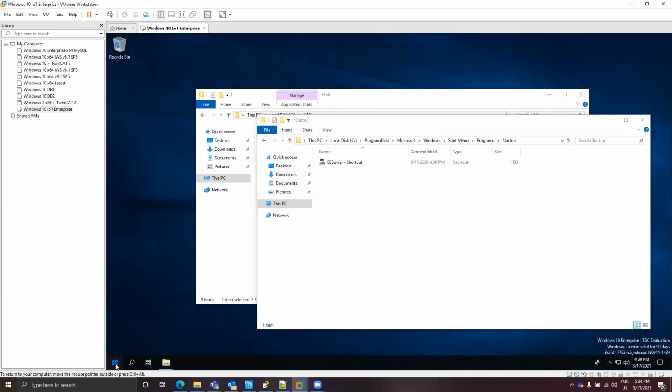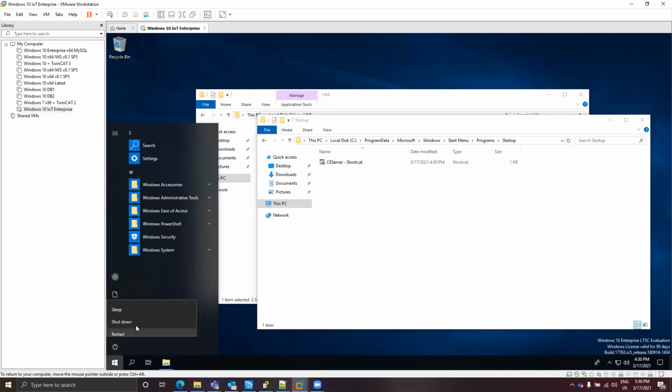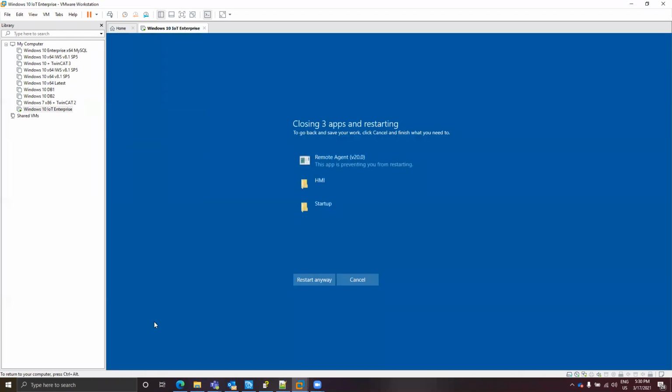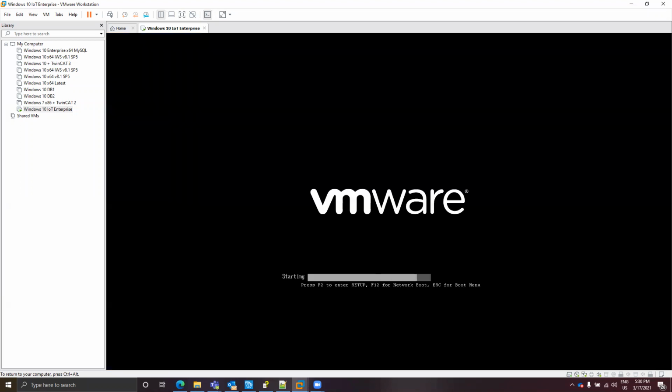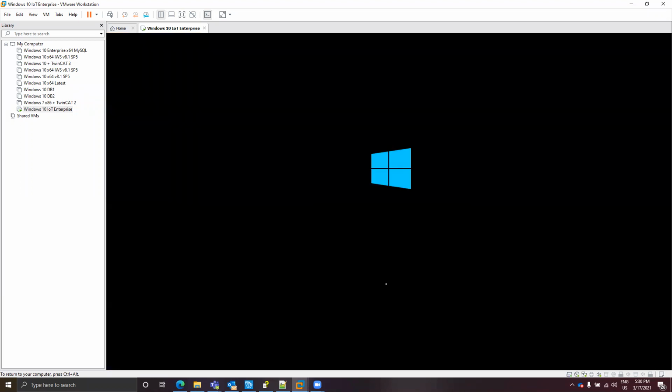After doing that, if you reboot the panel PC or it's restarted after a power problem, a power blackout, or the operator restarts the computer manually, and you want to have the InduSoft or AVEVA Edge application running automatically, you can do that. So let's wait for the station to reboot.